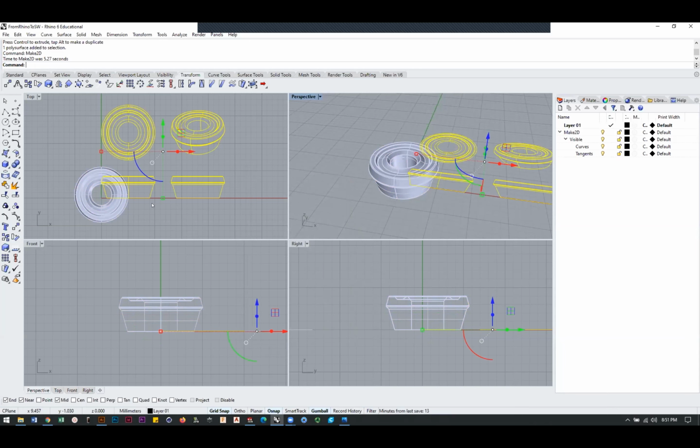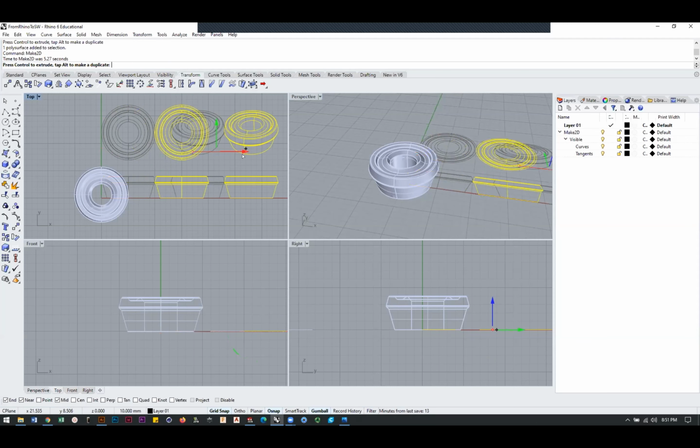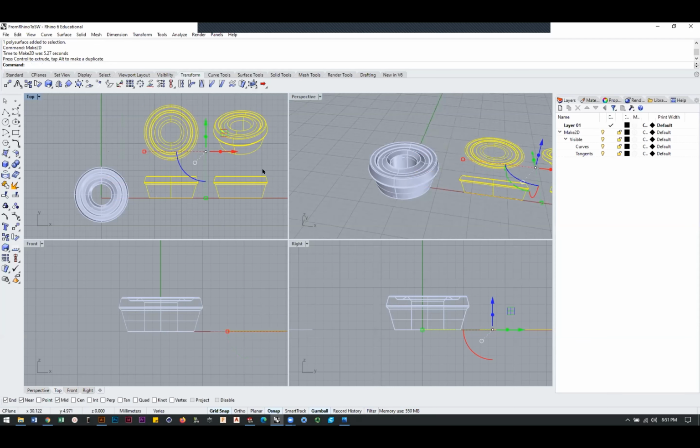It awkwardly makes it off to the side here, so you kind of have to know what it's doing. It arrives after you perform the operation, and if you don't group it or move it quickly and you click off of it, it all shows up as individual sketches. So you have to treat this as if you drew it by hand. It's all individual little bits of line work, which can be a good thing and a bad thing.